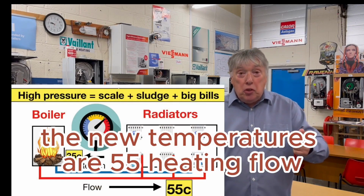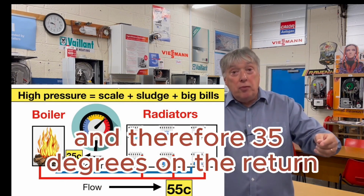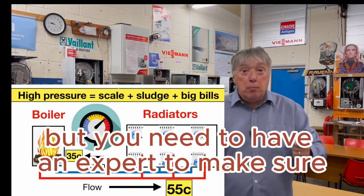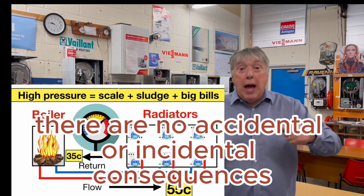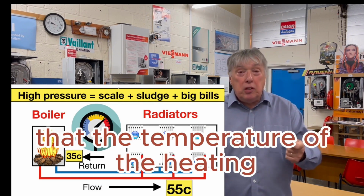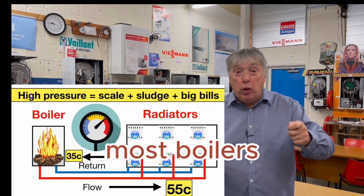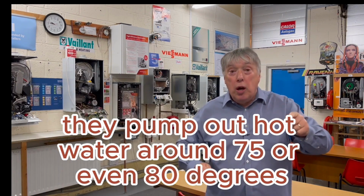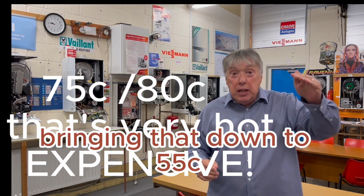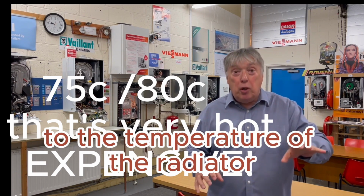The new temperatures are 55 heating flow and therefore 35 degrees on the return. But you need to have an expert to make sure there are no accidental or incidental consequences, that the temperature of the heating is going to be a lot lower, because at the moment most boilers pump out hot water around 75 or even 80 degrees. Bringing that down to 55 is going to make a huge difference to the temperature of the radiator.